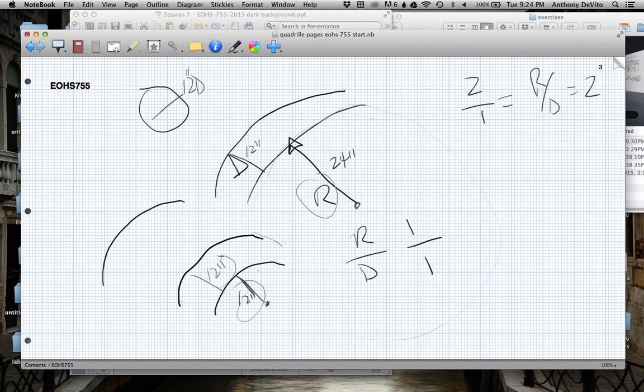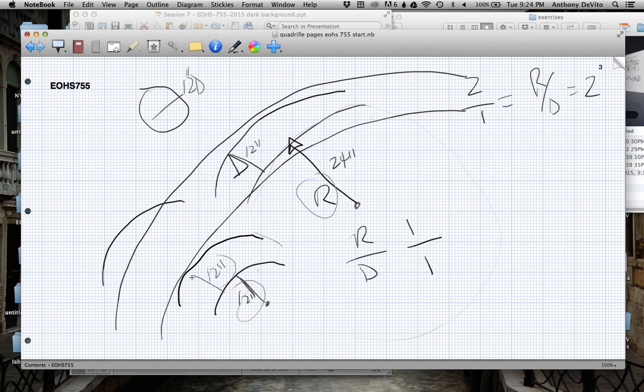They're both 12 inches, so it's a sharper turn. Where you could have a really slow turn, if this is 12 inches, it makes a 90-degree turn, but the radius is very large. It's like going around a much larger curve. Go around a tight curve, you feel the G-forces a lot more. Same thing with the air. That's basically what's happening with the air.